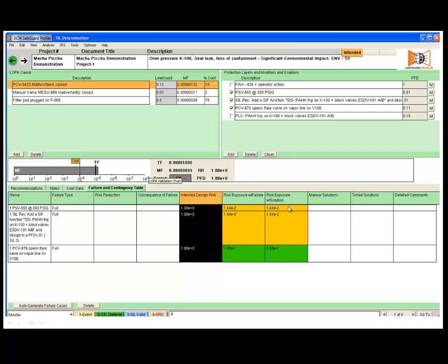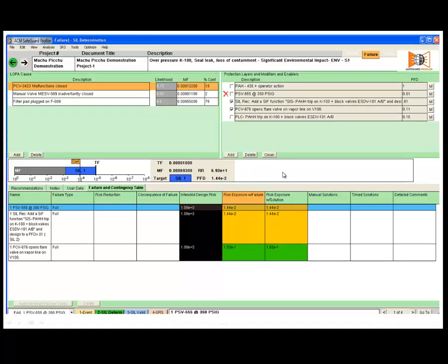That means the solution if you implemented a contingency. So for example, you click twice on the risk exposure with failure, it would fail that safeguard, the first one in there, and tell you that you're exposed now and you have a SIL1 exposure 1.44, for example, 10 to the minus 2. So you have your failure exposure there.